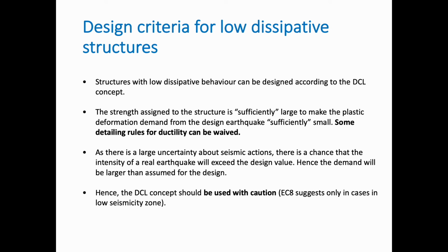In other words, the low dissipative concept should be used with caution. Eurocode 8 suggests it only in cases of low seismicity zones. Because of this uncertainty and because we're not really using the ductility of the structure, we should be cautious with how much we over-design and in what kind of structure we use it. I would say low seismicity zone and really low height structures.